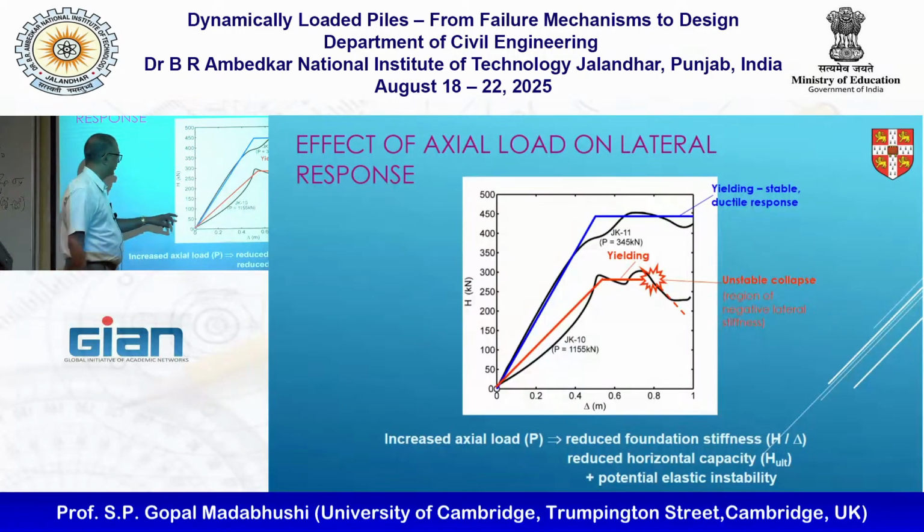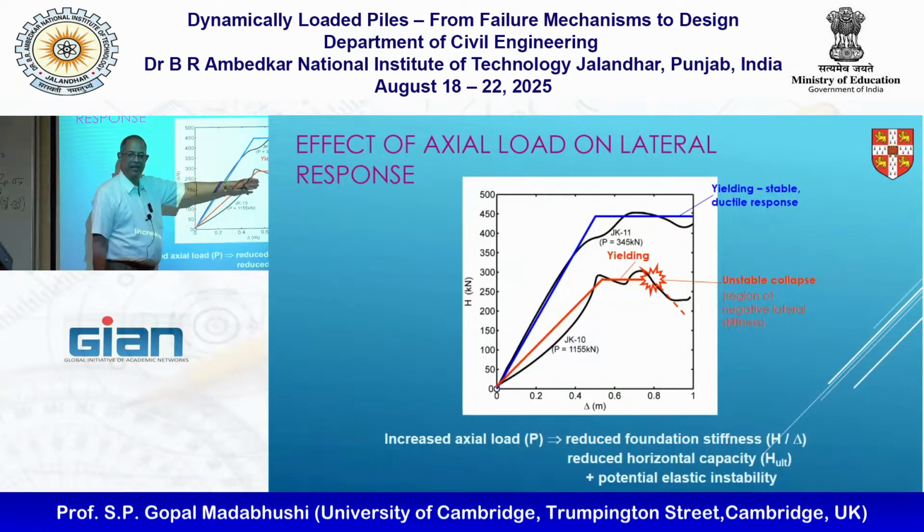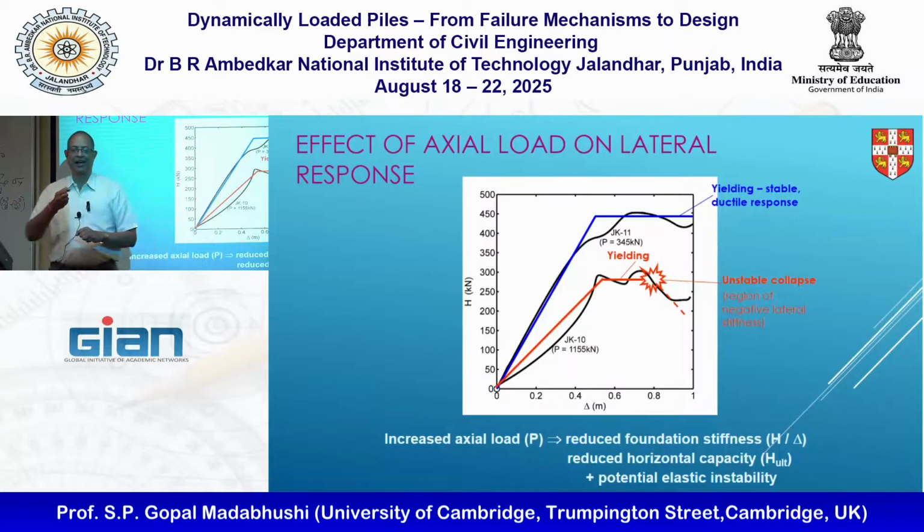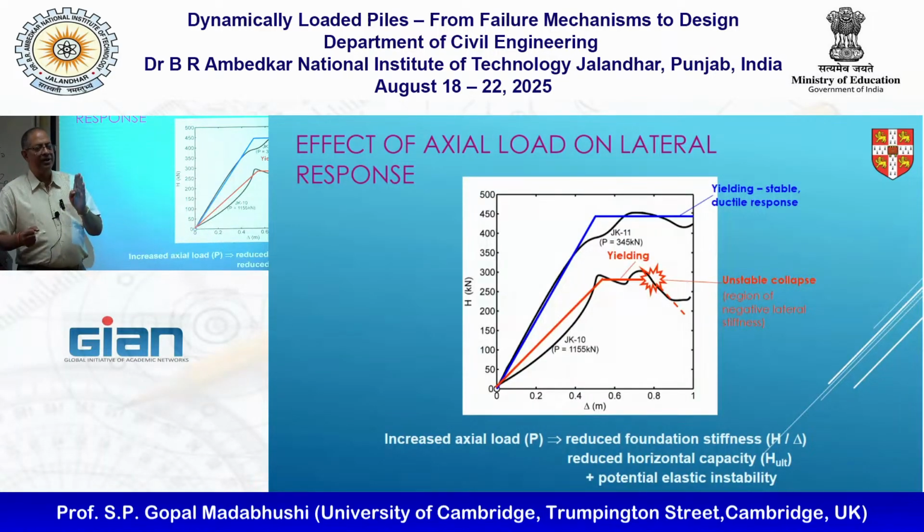The actual experimental ones are in the black. Okay, they're not perfectly like that, but they're not far off. In fact, I would say it's pretty good. So if I make my axial load smaller, then I'll follow more or less the blue line, reach some peak, and I will get slow yielding of the pile, and it will continue to deform as the plastic hinges form because my axial load is relatively small.